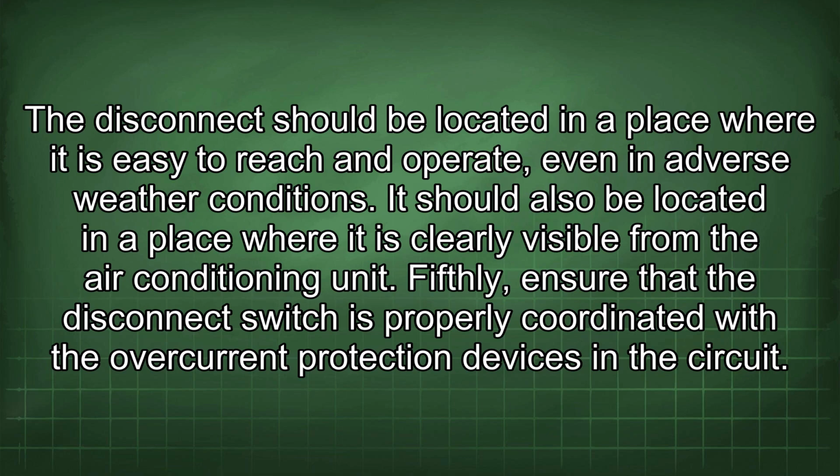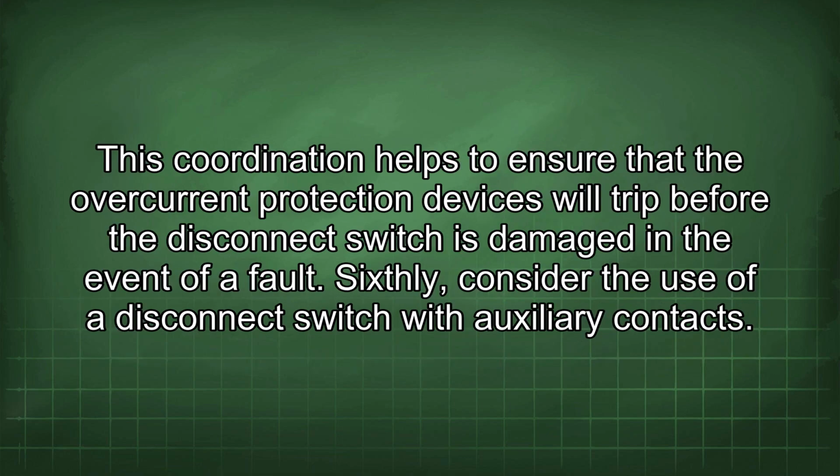Fifthly, ensure that the disconnect switch is properly coordinated with the overcurrent protection devices in the circuit. This coordination helps to ensure that the overcurrent protection devices will trip before the disconnect switch is damaged in the event of a fault.